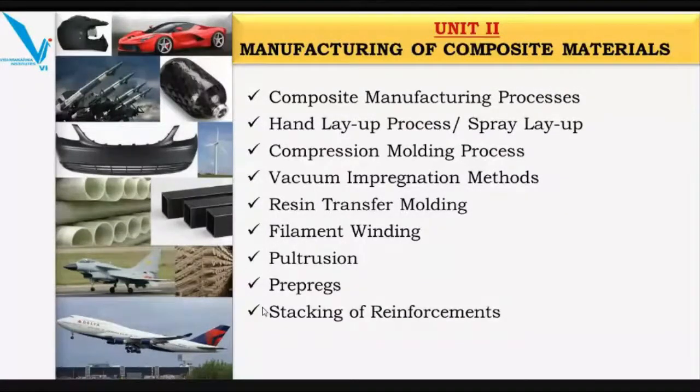Beyond that, other techniques were developed: compression molding, vacuum bagging method, resin transfer molding, filament winding, pultrusion. It is also called pultration. Basically, we are pulling the fiber here. So pultrusion, that word is from that. Just see what the pronunciation is.